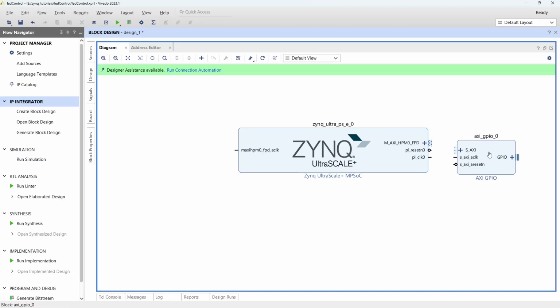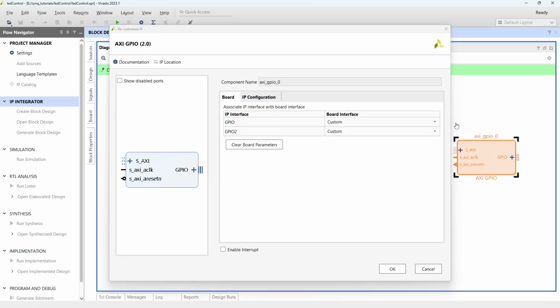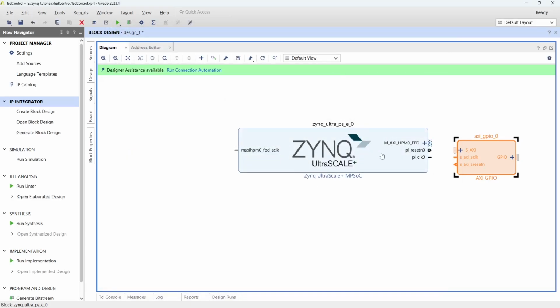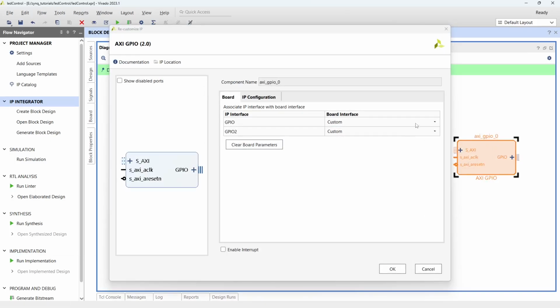If you look at this AXI GPIO, my target is to connect the LEDs to the SoC. So LED is actually an IO device and it should be connected to this SoC. For the SoC, here actually we are using the concept of memory mapped IO. So this will be a memory address. These LEDs will be just a memory address for your SoC. So GPIO will have some memory address and the SoC will be communicating to the GPIO. It will be simply transferring data to that particular memory address. And we should ensure that this GPIO is connected to the LED.